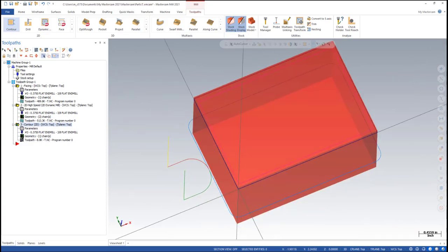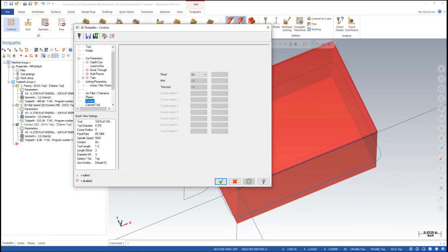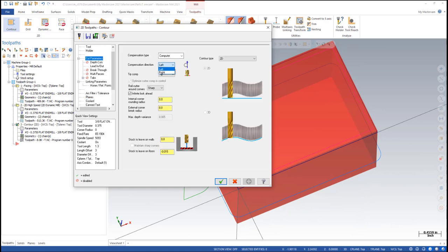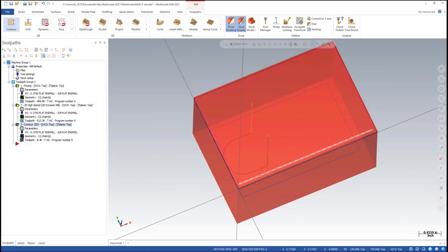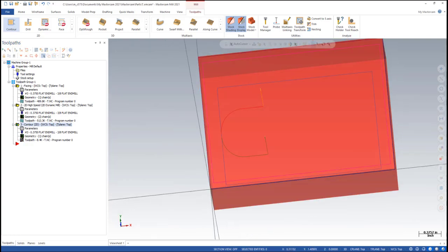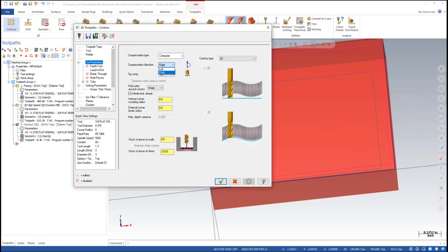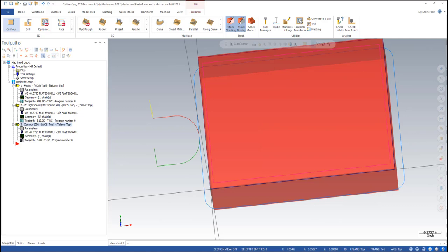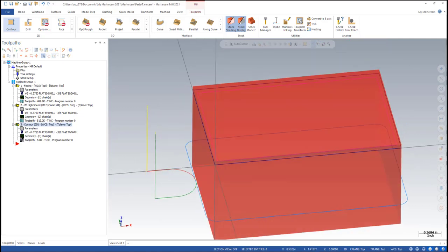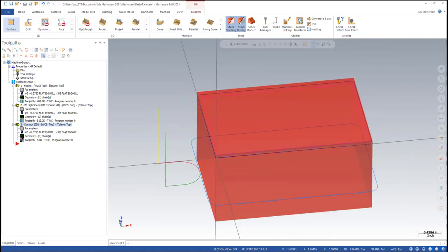And if for whatever reason you had your cutter comp on the wrong side, so if you had it on the right side and you generate that, it's now cutting on the inside of the box, which is wrong. We're not trying to do that. So just always be aware of the direction your tool's traveling in these tool paths. You can't just tell it, I want to climb mill, and then expect the computer to figure it out for you. You have to specify your chaining directions.